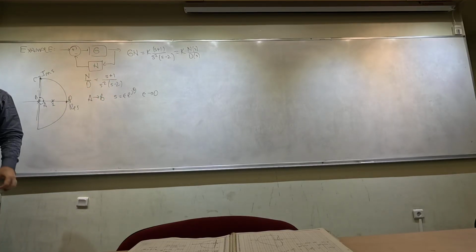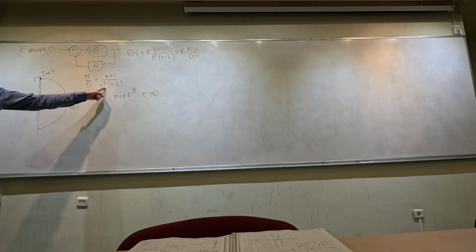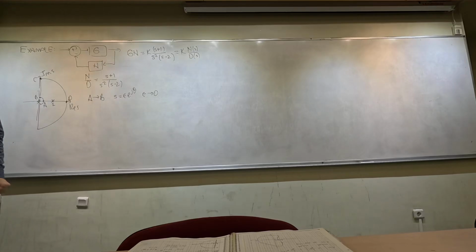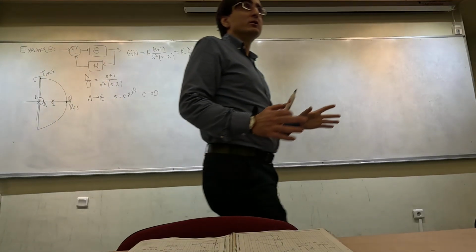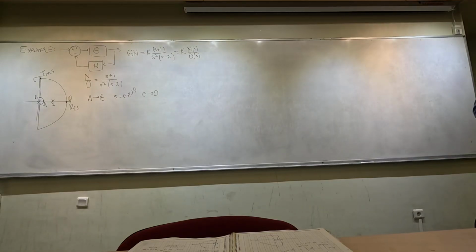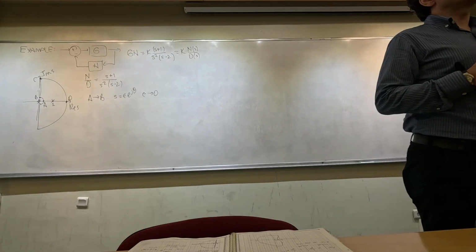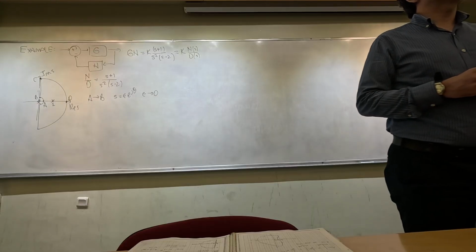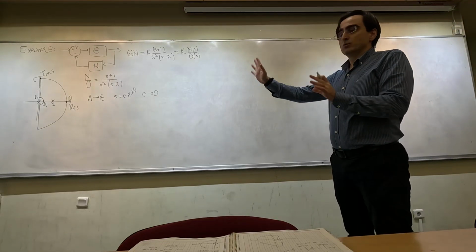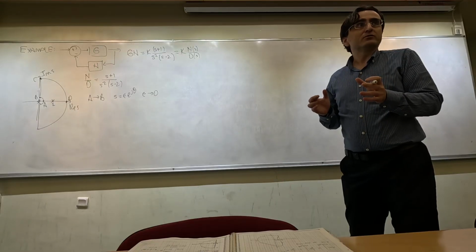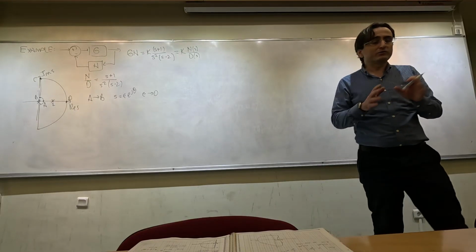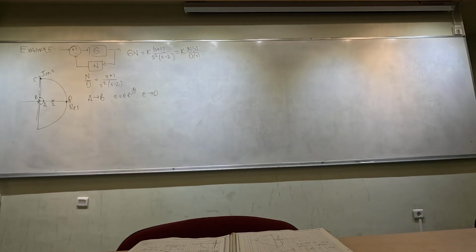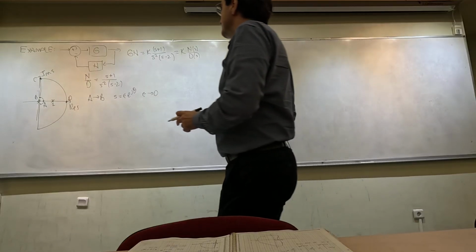Its Bode plot is going to be given to us, and we will design our closed loop controller using that Bode plot. In root locus, we did the same thing. We were given the open loop transfer function, again the same thing, and we found closed loop pole trajectories. Doing the same thing over and over. In state space representations, the last topic of this course, we will be given the state space representation of the open loop system. Then we will design a feedback rule, and we will try to optimize the closed loop state space representation. So everything over and over, but with different representations of the systems. Each part of control theory is based on some representation of the system, and using different representations, you can try to achieve similar aims.